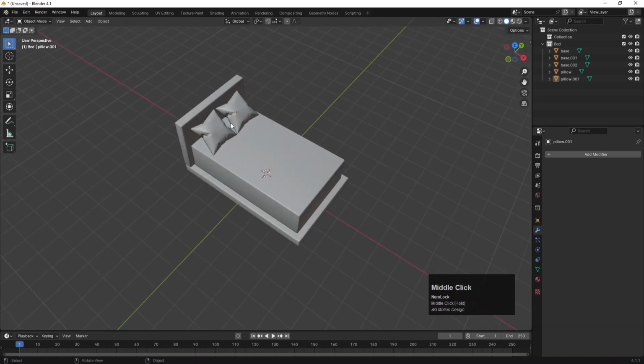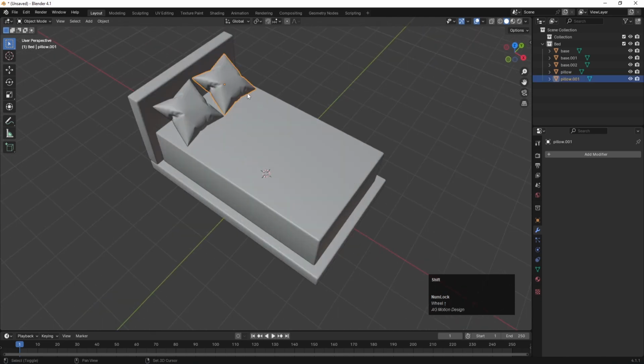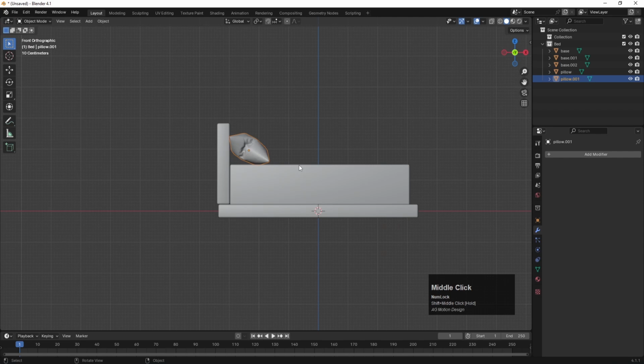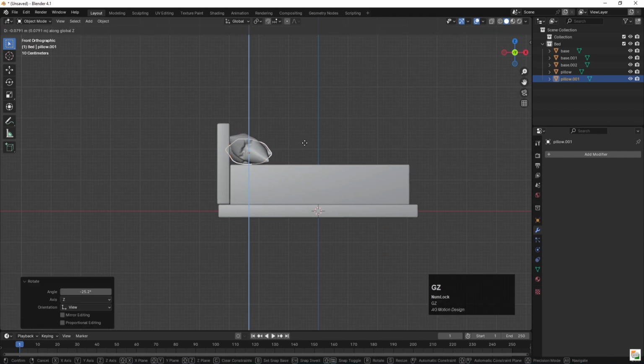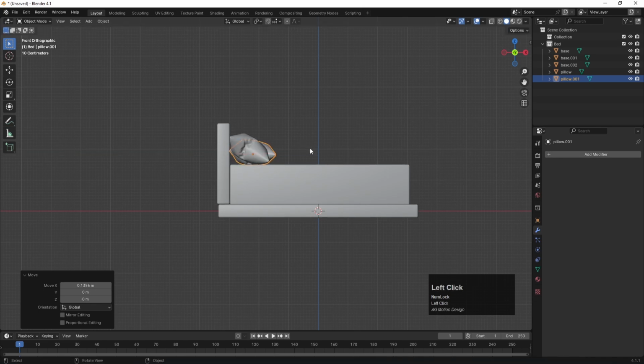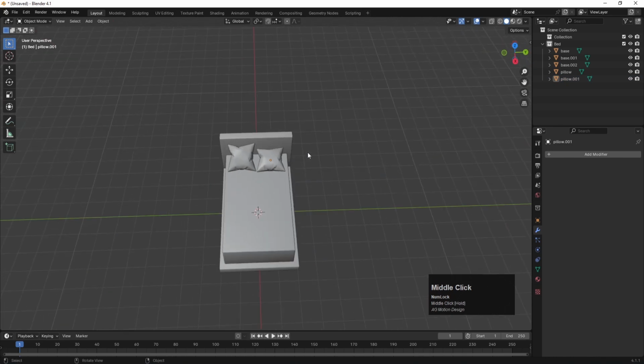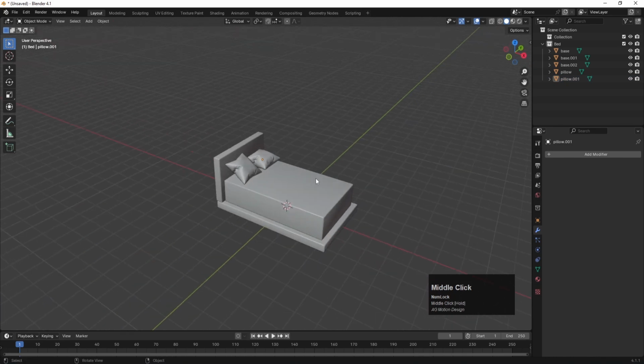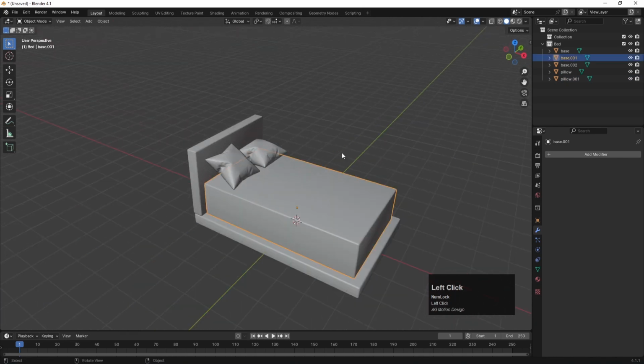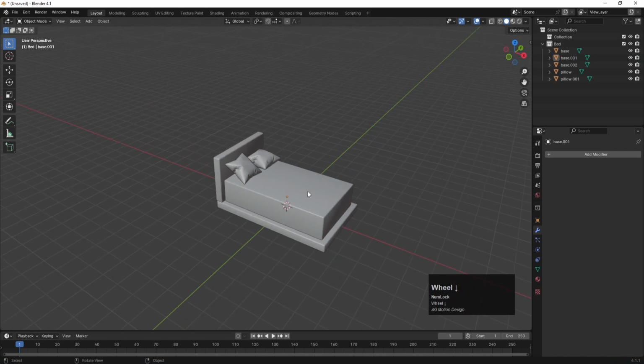Okay, if you want, then you can select this and let's go over here, press R for rotation, and let's rotate it like this, G Z, and try to adjust it over here, G X, and try to adjust the position over here like that. Okay, so it's totally up to you, the way you want to adjust the position, you can adjust that like this. Okay, now let's try to animate our cloth again.